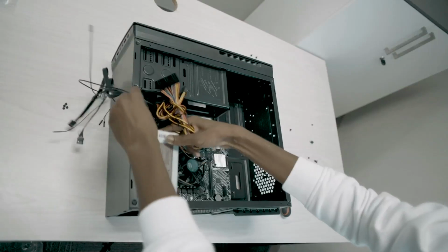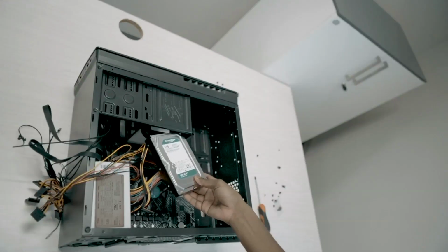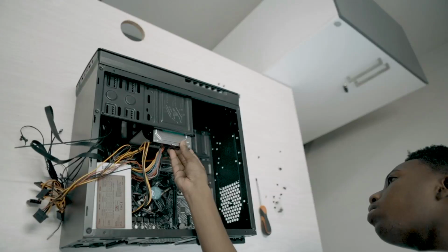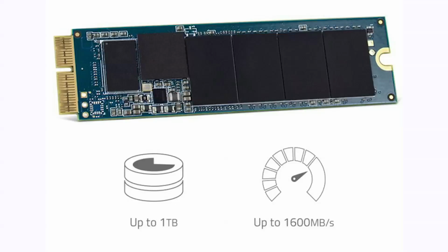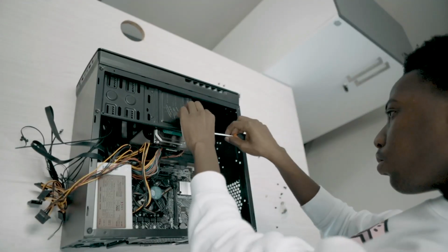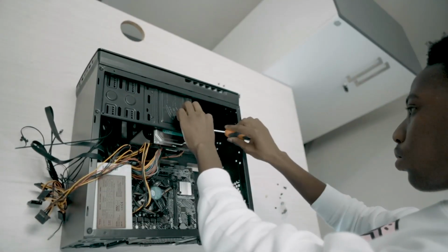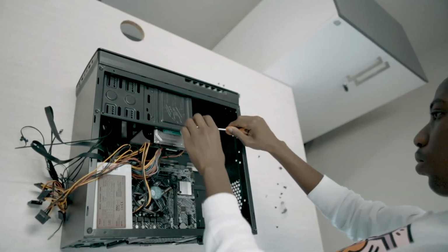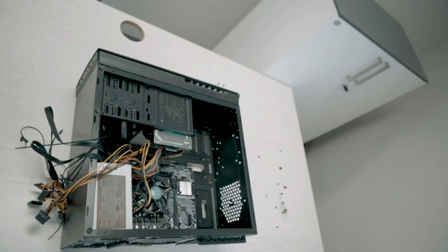Install the PSU. Mount your storage onto your PC. This varies depending on your case and storage type. An M.2 SSD plugs directly into your motherboard, while most others can be attached to your case via screws or special slots. You'll attach them to your motherboard via cable later.